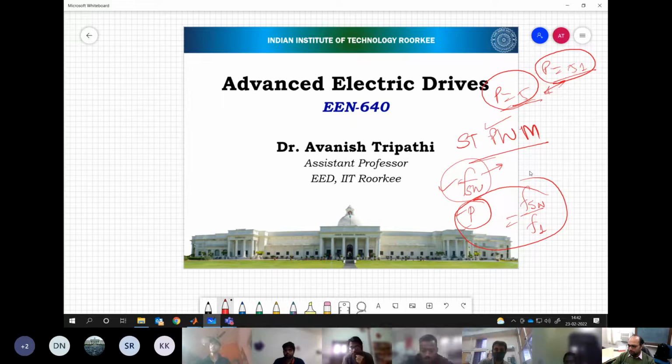So when you go to industry or start working on your projects, when you have a motor and you want to run it with an inverter, the first thing you have to decide is what should be the value of DC bus voltage. You cannot feed just any voltage. Many times we see students during their MTech presentations simply keep VDC as 100 volts for a 400 volt line to line motor. And some people will have sine triangle PWM where the spectrum is so bad that you cannot say what they are doing. They have no idea; what MATLAB gives, that's all. They take that as the correct answer.